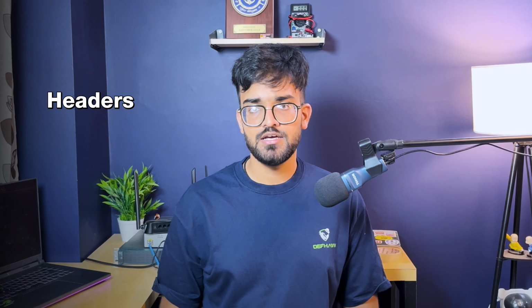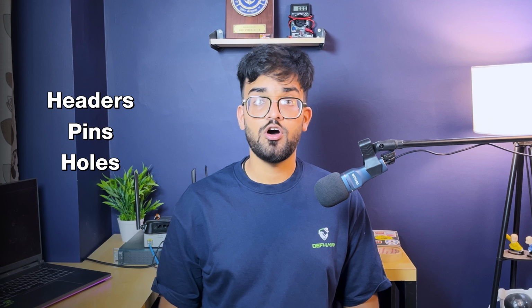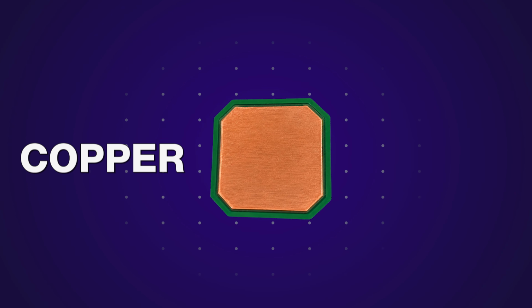These contact areas, which could be in the form of headers, pins, holes, or they might not be labeled at all and are just copper pads, have to be connected using something known as a serial to USB converter. This could be an adapter, it could be an Arduino, or anything else that might be present. Now, the issue, as mentioned before, is that manufacturers are no longer labeling them. So how do you figure out which is which?